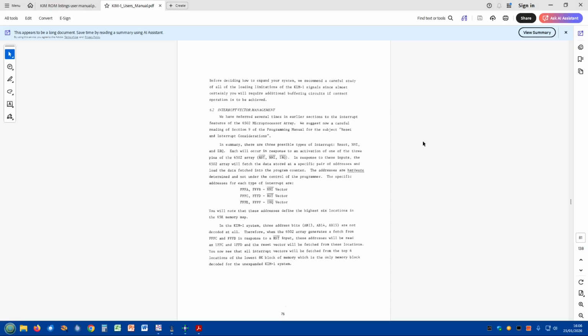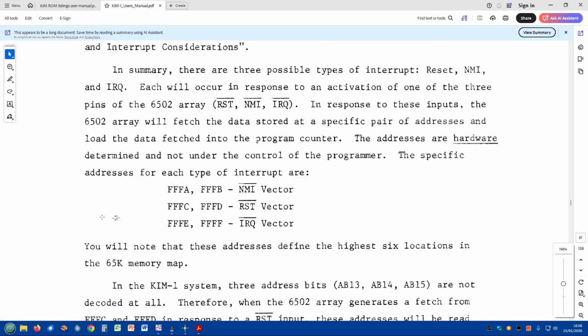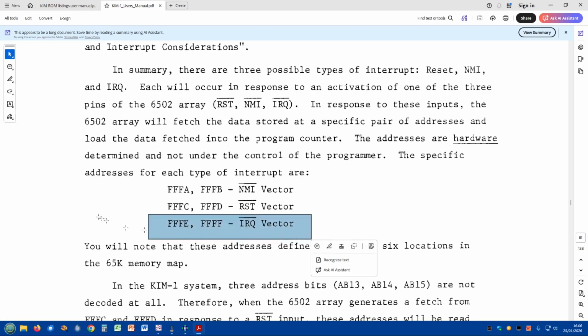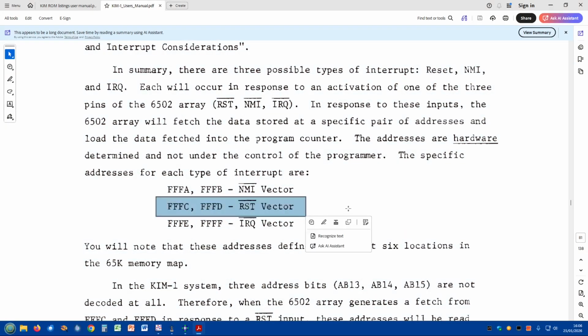So here, this is where we got the startup vectors. Let me zoom in a bit. This is the top of ROM. The 6502 will first of all go to this address and load in those vectors and store them away. And then it will collect this one, and that's the reset vector. That goes into the program counter for startup.